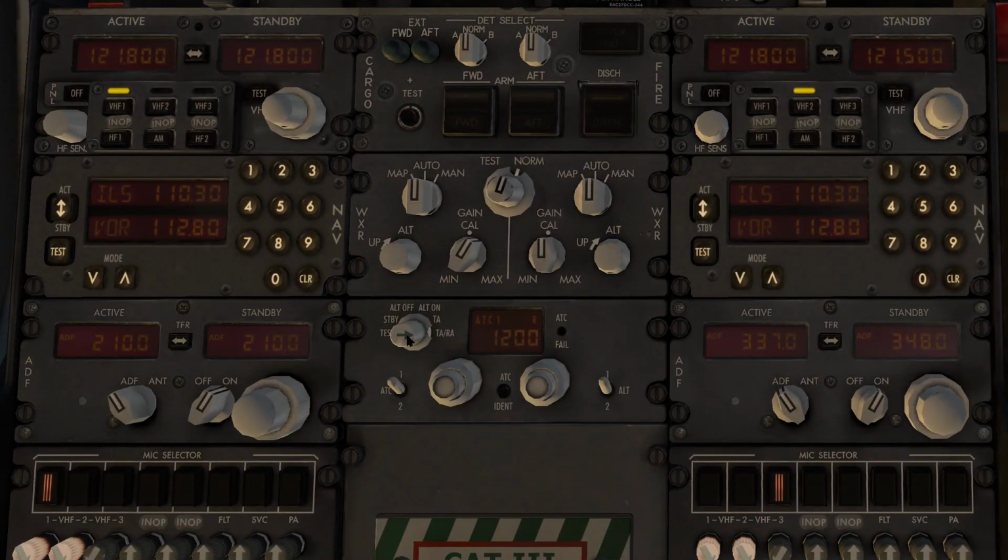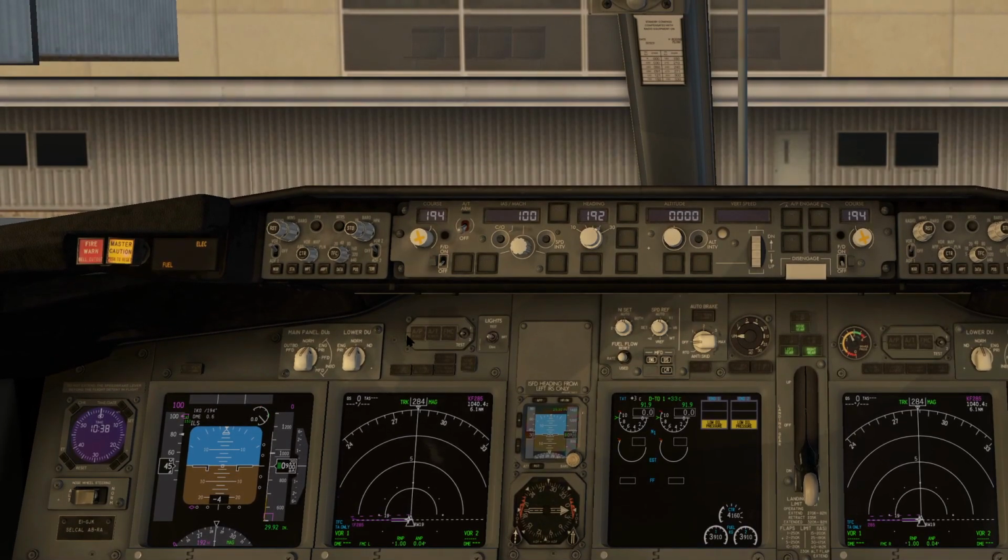And we are now ready for starting the APU. Now, because this is a long flight over the ocean, we cannot really use VOR navigation, so we will have to use LNAV and VNAV. So everything is set in the FMC for that, so we can pre-arm flight director on first.